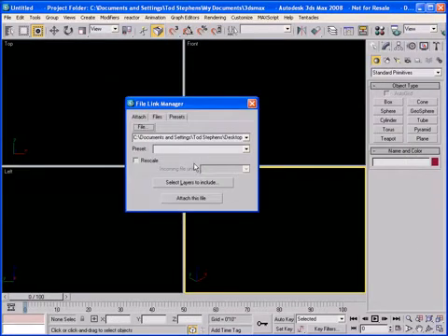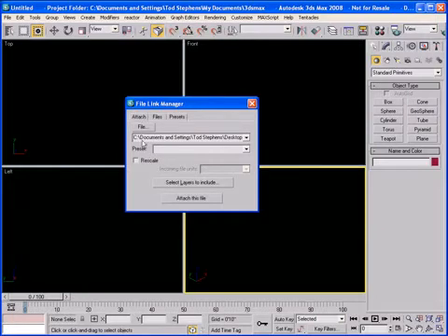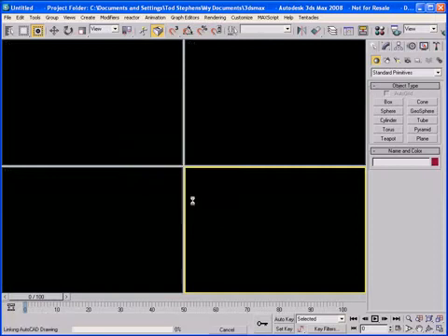Then a couple other settings we have to look at. Under the Presets tab here, just make sure Revit is the preset that's highlighted. I'm going to allow the presets for the geometry to work from Revit. Click on the Rescale button. Notice incoming file units changes to inches, again just to keep everything to scale. Then I click on the Attach This File button, and now we're linking that DWG drawing we exported out of Revit and pulling it into Max. So pretty quick process.